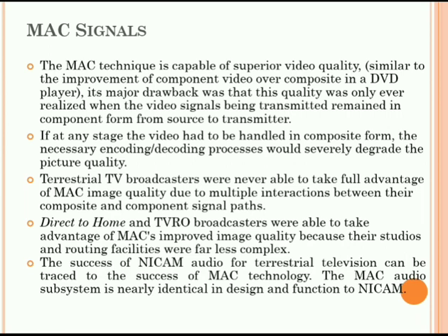The terrestrial TV broadcasters were never able to take full advantage of MAC signal quality due to multiple interactions between the composite and component signal paths. Direct to home, that is DTH, and TVRO broadcasters were able to take advantage of MAC's improved image quality because their studios and routing facilities were far less complex.